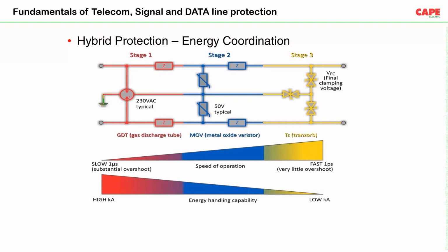For all these things, we have different kinds of SPDs. That is, we have to use a different impedance for different applications based on the frequency and the requirement of the system. So a good manufacturer will have different models with different impedances. Now, if a manufacturer claims that it has a universal SPD that works for almost all communication or signal lines, probably that manufacturer will be using a gas discharge tube, and the other two components will not be used in that device. And for signal and communication line protection, a GDT typically has a very high voltage clamping rating. Hence, equipment will be under very high stress. It will experience very high voltage even during the surge.